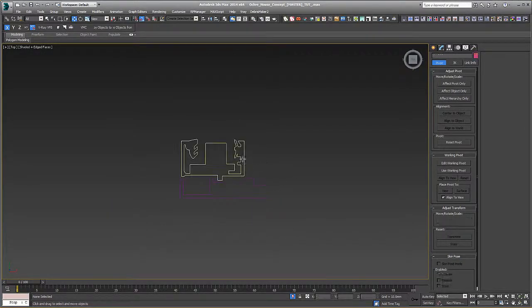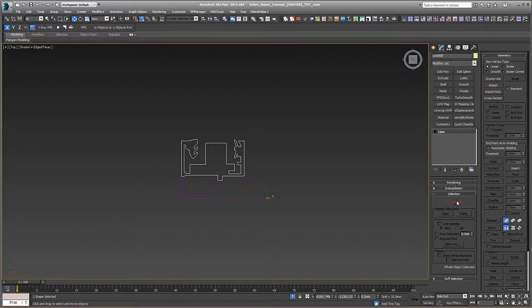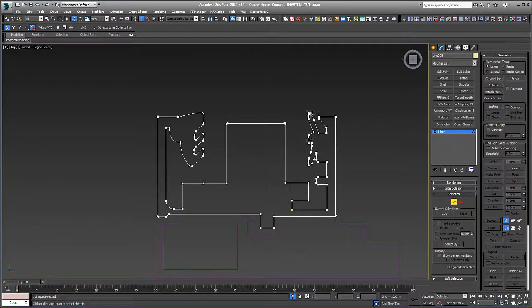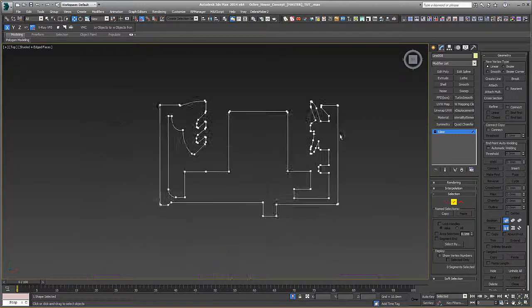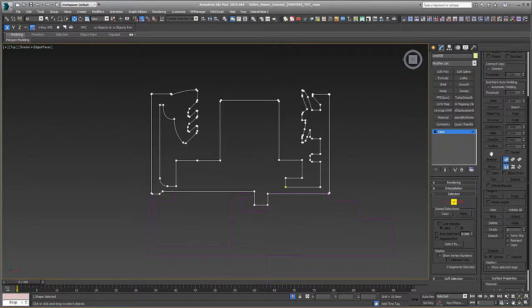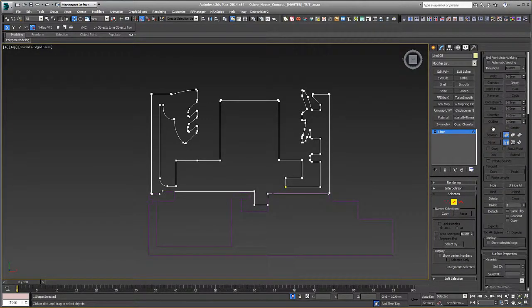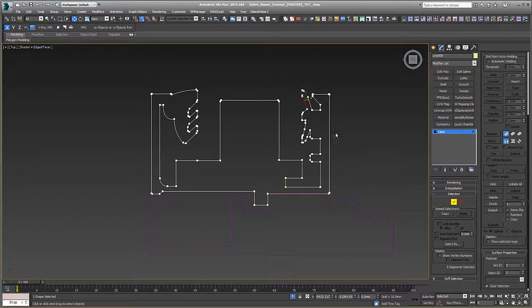One little tip that I always use when creating windows this way is that you can give splines IDs, the same way as you can give polygons, which I'm not entirely sure how many people know. It was something I learned on my placement year, and it has always come in handy. I can pick edges and, as you can see, surface properties, material IDs, ID1, ID2.